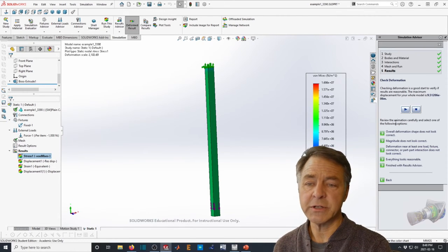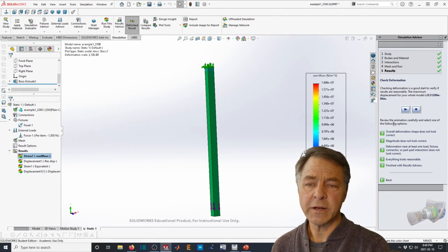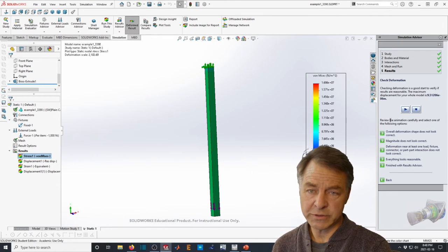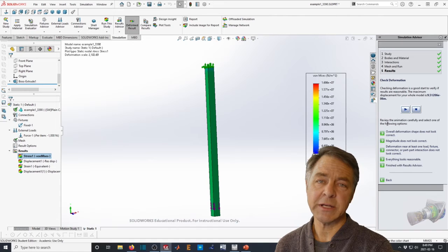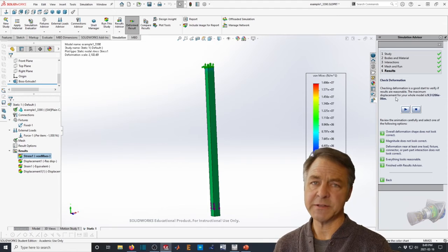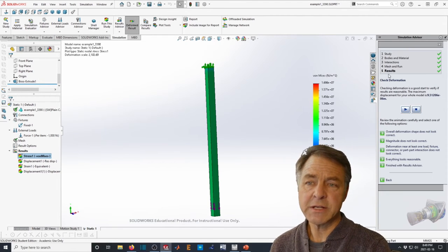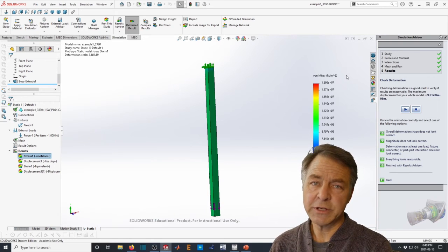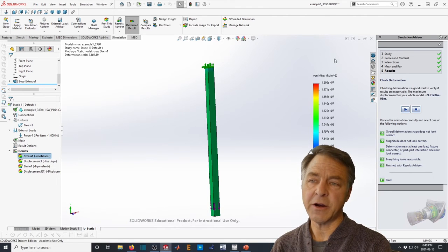So in this model, we could look at those values that we've constructed, where we got 9.52 microns with our hand calculation in terms of the change of length of the bar, the stretching of the bar. We got 9.511 with our coarse mesh initially, and now we've got 9.512 with a finer mesh. And we could plot those results and we could see generally a decreasing change. And with that decreasing change, we could start to look at that and say, well, what should be the right size mesh for a model like this? And that's how we're going to validate all of our simulations, is looking at variations in the boundary conditions, variations in the meshing, and looking at levels of complexity that are and are not useful.